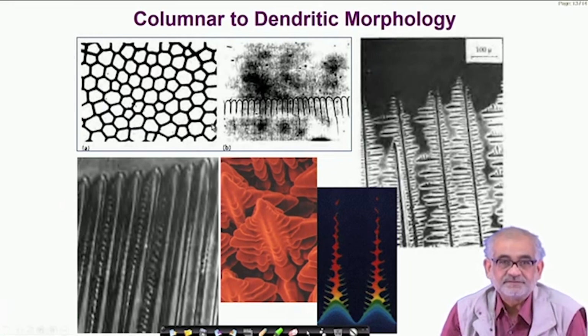For solidification processing, we have to realize that as soon as the hot metal or hot melt comes in contact with the solid mold, heat transfer starts immediately, and that's when the heat transfer rate is the fastest. So we first get very ultrafine structures, followed by gradually rather coarser structure, and finally in the middle we are likely to see such equiaxed zones where the tendency of growth or the rate of growth of the crystallite in all three directions would be about the same.